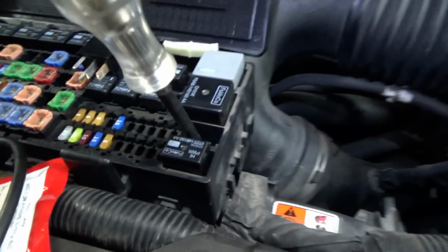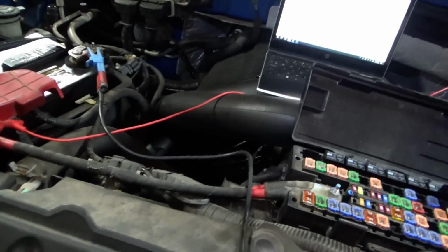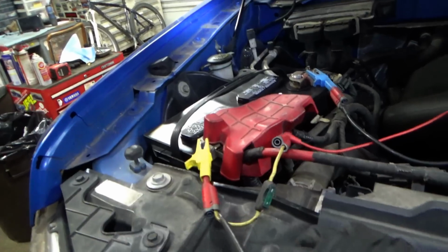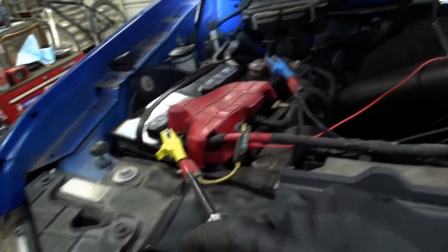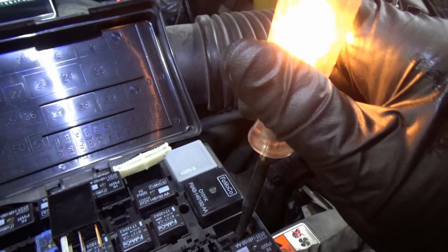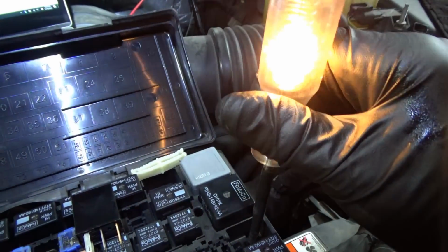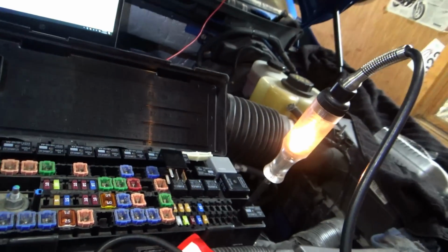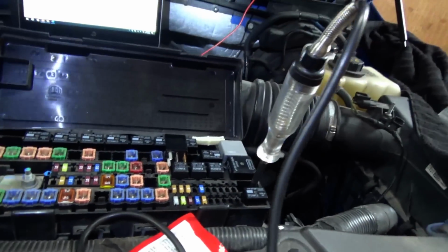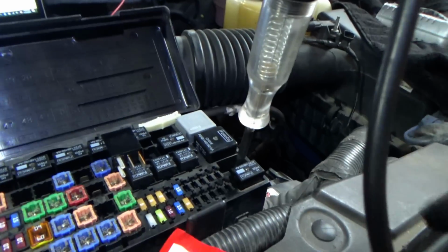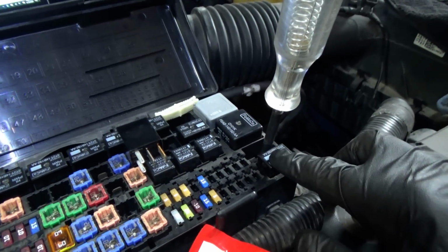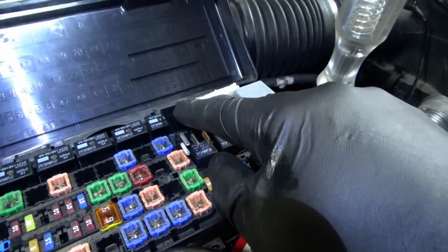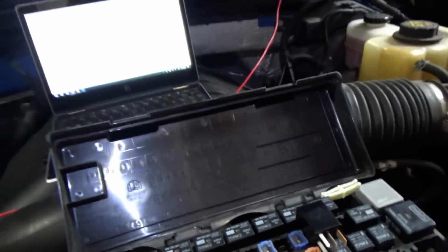No test light. So indeed we have a broken wire. See, that works. Oh, now that does work. Now both pins are hot. So if I keep my test light in there and disconnect this power, okay, so my initial suspicion was actually wrong. The load side is perfectly fine. So either a bad relay or something wrong on the control wire.